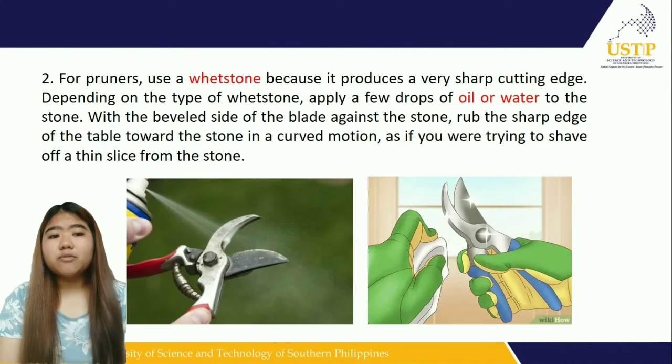Rub the sharp edge of the blade towards the stone in a curved motion, as if you were trying to shave off a thin slice from the stone.